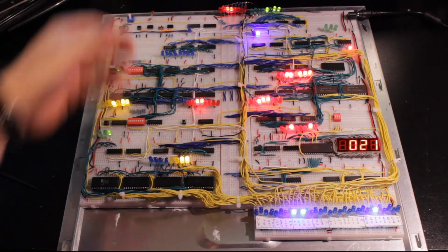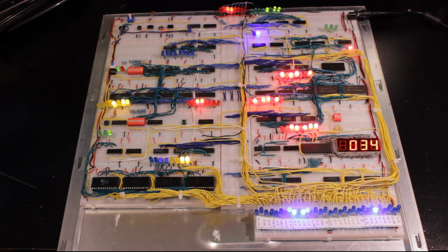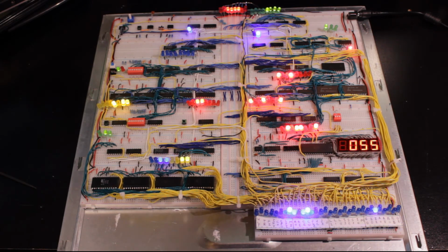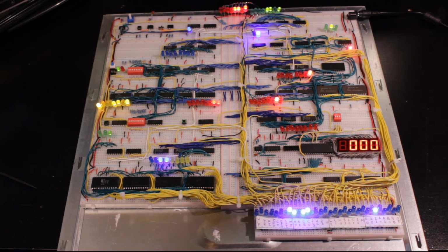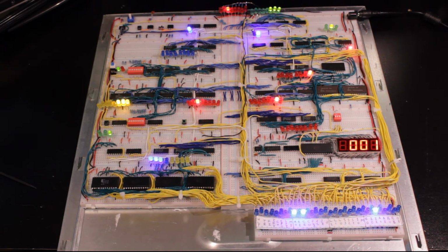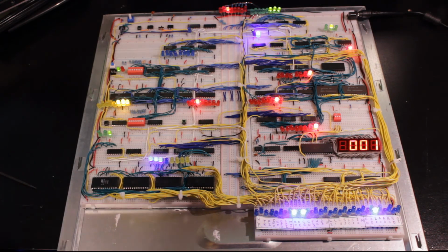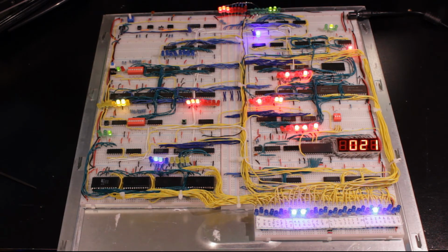You may notice 2 new LEDs and another chip up here in the right hand corner. I actually noticed that I forgot to add a multiplexer circuit to calculate the carry flag on the bit shift ROM's operation. So it's just multiplexed with control signals from L2, L1, L0, which control the bit shift operation, and based on those it selects what value it's getting the carry from. For example, if we're shifting left, then it takes it from the most significant bit. If we're shifting right, it takes it from the least significant bit, and if we're not shifting, it takes it right from the ALU.